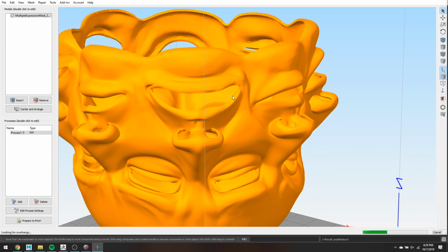You can also actually use that if you want. Say my print failed, and I just chose to rip it off the build plate and reprint a new one, or a new piece of the head. But if I knew pretty close to the exact layer height where it failed, I could theoretically set the start printing height and have it print a new model on top of the existing one and splice it together. Theoretically. I've never tried it. It just seems dangerous to me, but you can do it.